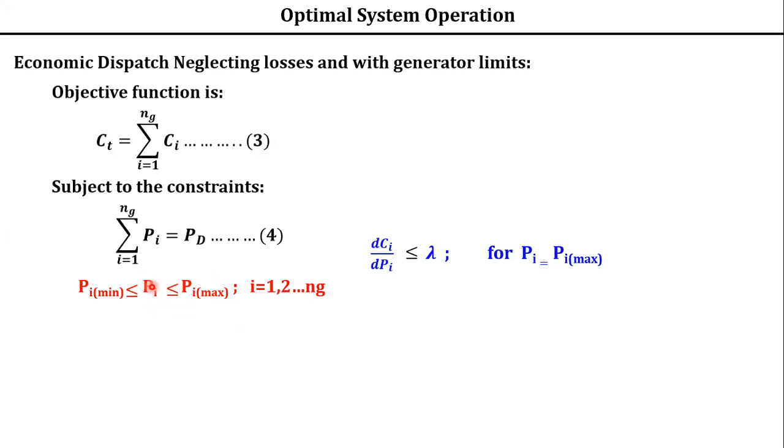So obviously it has violated the upper limit, because based on this one only we are going to solve one numerical. So that's why I'm telling it. So it will be pegged at maximum limit. That means even though the calculated value here is 110 megawatts, the maximum value is 100 megawatts. So PI will be clamped at 100 megawatts only.